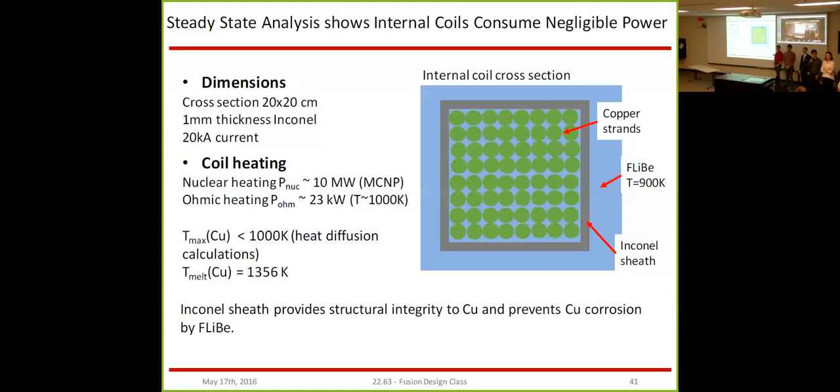Yeah, so one thing we didn't explicitly talk about today was including sets of manifolds around the device. So we have 18 toroidal sections, we have these poloidal cooling channels throughout the whole vacuum vessel, and incorporating overlapping manifolds would hopefully ensure that if one pump would fail or a pipe becomes stagnant, then another pump could take over the response, you know, for that extra.